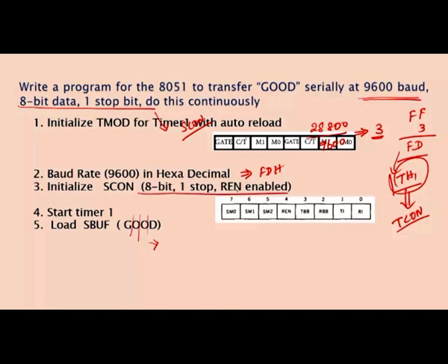So, for the given specification in the SCON, first I have to give it as 8 bit, meaning these two are 0. The interrupt is also initialized with 0, then the receiver enable is 1, activated in mode 1. So 0 1 I will give it. So the value is 50 H. So 50 H is to be loaded in the SCON.